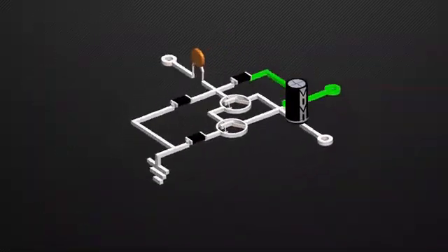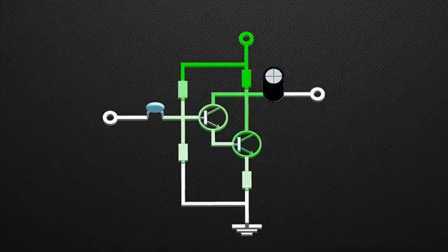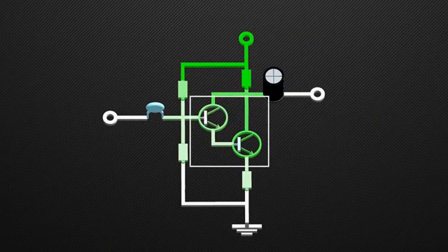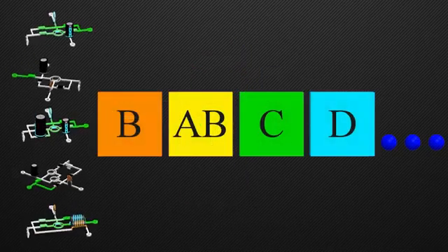This circuit uses the Darlington transistor in place of the single transistor. Darlington transistor is two transistors within a single package, one small pilot transistor, and another larger switching transistor. This increases the current handling capacity and gain of the circuit. Also, this provides high impedance at the input and low impedance at the output.